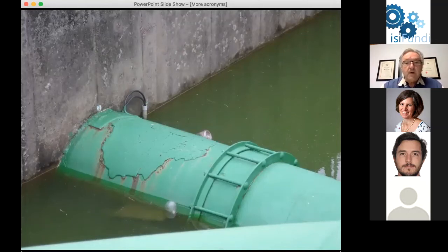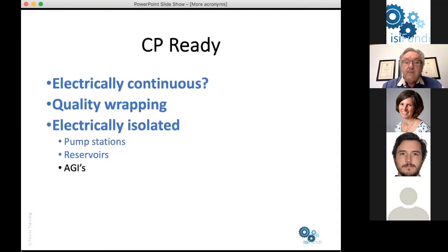with the steel reinforcing. This is in fact a major challenge with pipeline construction. We've had a couple of instances where a random connection between a piece of reinforcing and the pipeline has caused major hassles because it has drained the current from the pipeline and resulted in a lot of expense to try and find the drainage point inside this reinforced concrete. These have been water pipelines. Gas and oil pipelines have nothing different.